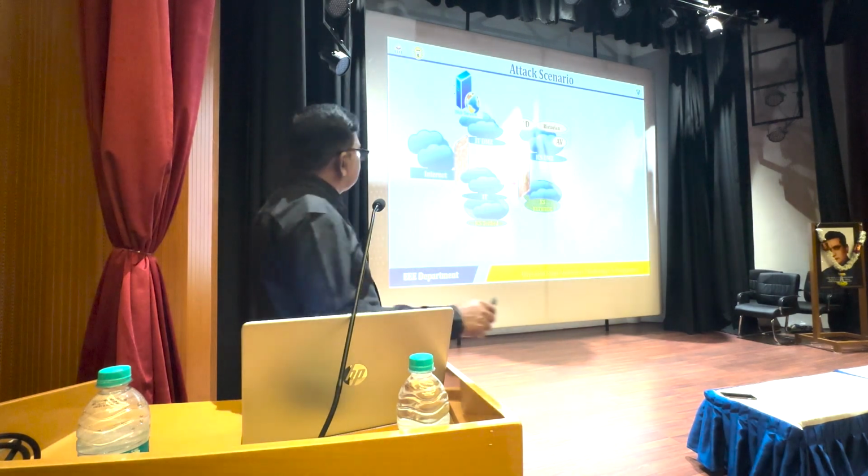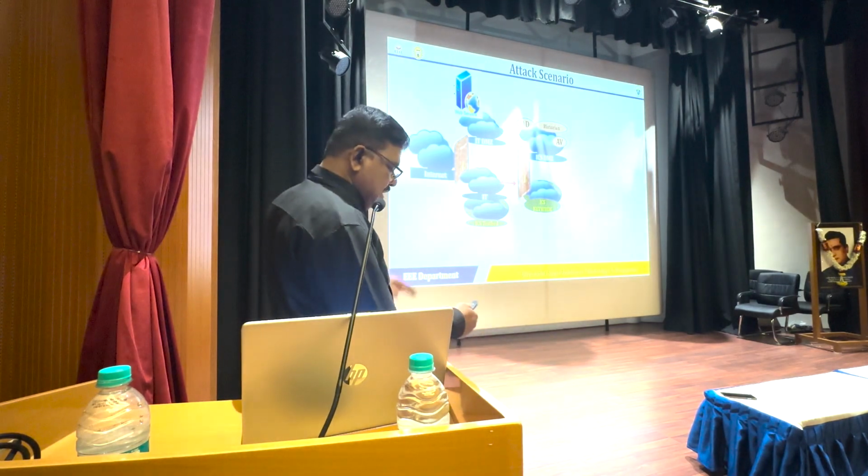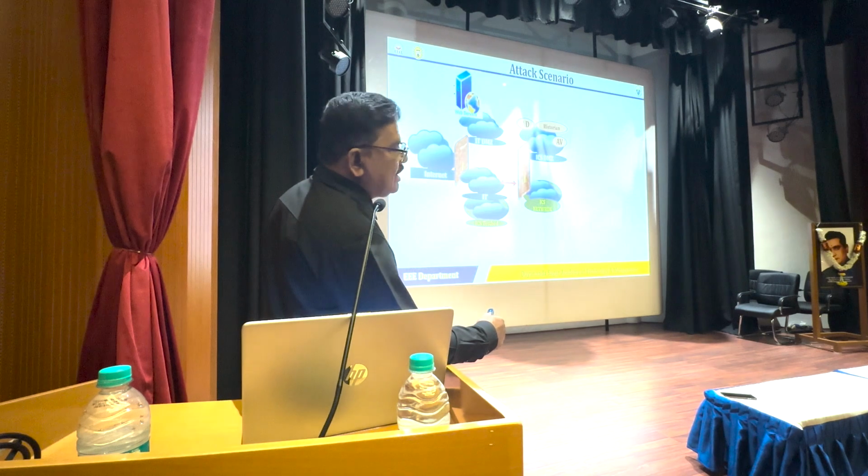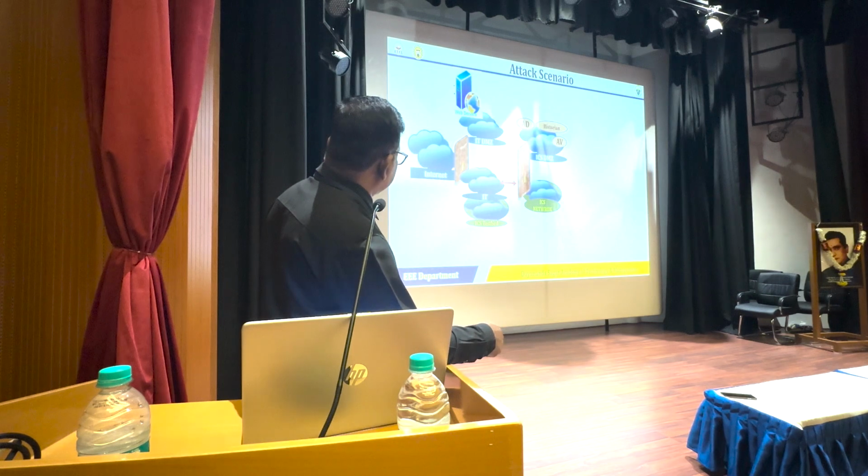Now up to this point, I can say, through the internet, then you have a firewall here, then the IT DMZ, information technology demilitarized zone. This is known as the demilitarized zone. This is an additional security layer, which is not exposed to the external network. And we'll have a web server. Then we'll have information technology, then the ICS test bed. Then again through the firewall, we'll have the industrial control system demilitarized zone, then the industrial control system network, then antivirus, historian, etc.